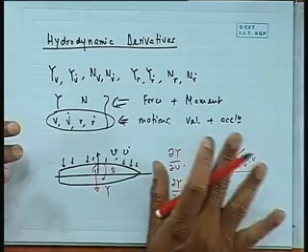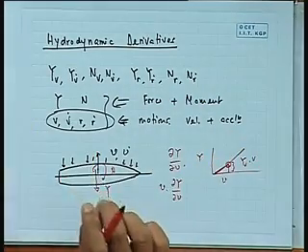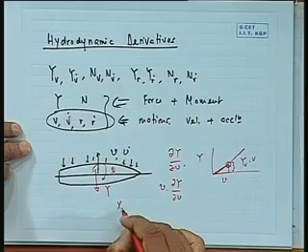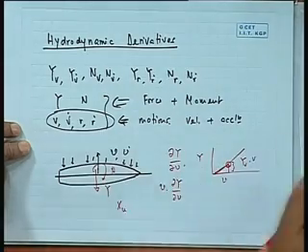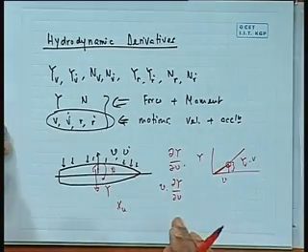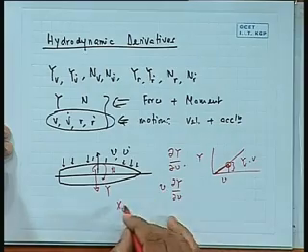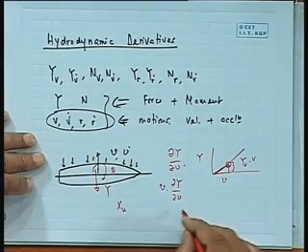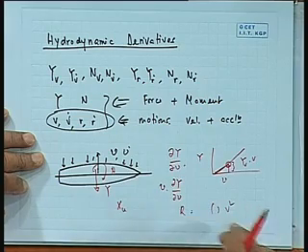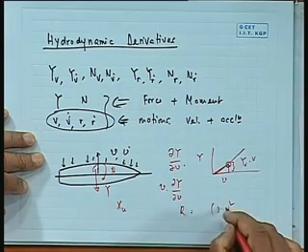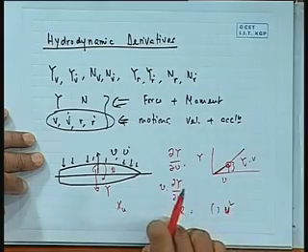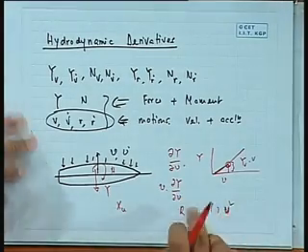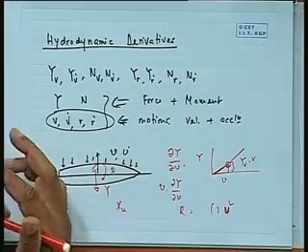So, hydrodynamic derivatives essentially are hydrodynamic forces that are introduced on the body because of the introduction of some motions. In fact, you can call the resistance also an Xu hydrodynamic derivative, because it is the x force because of u velocity. In a sense, one can always say that resistance is something into v square, or u square, let us say forward velocity. That means you can say that there is a coefficient of u square. So, one can also think in terms of a derivative. It is something similar to that.